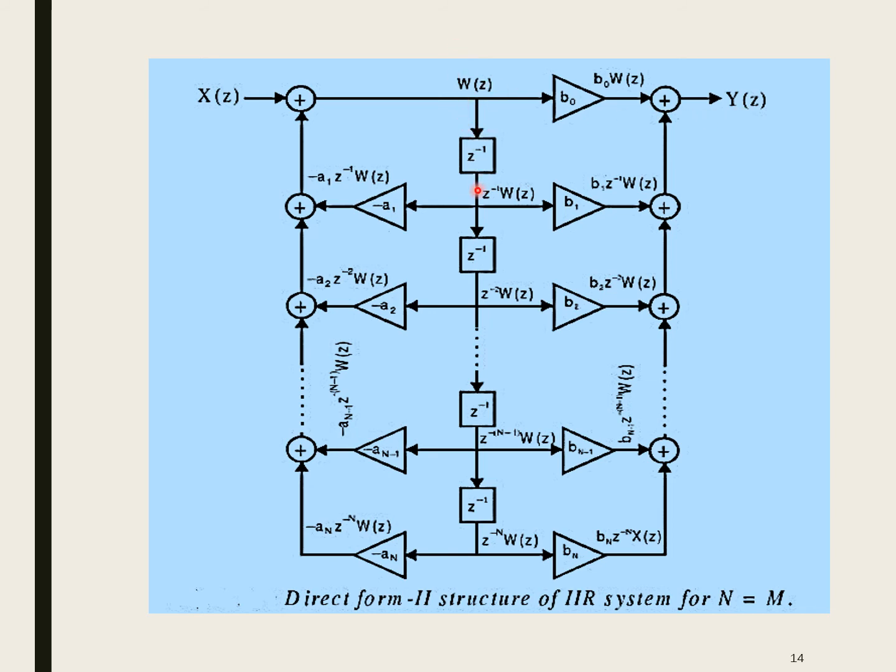So using that, we can use this structure to obtain direct form 2. So this is the generalized structure, and here we can simply look at, capital N is equal to M. So this is a perfect canonic structure, whereas direct form 1 cannot be a canonic structure, because the delay elements and the order of the system will not be equal in direct form 1. Okay.